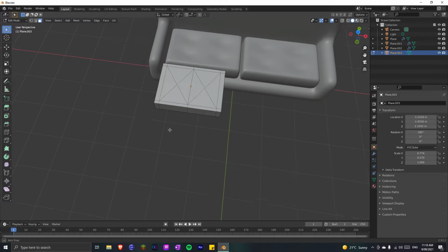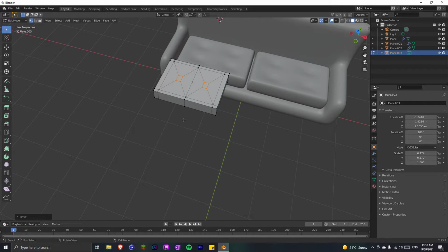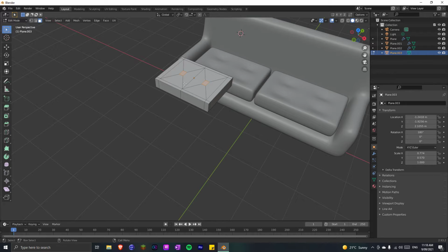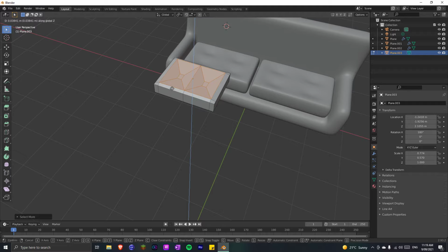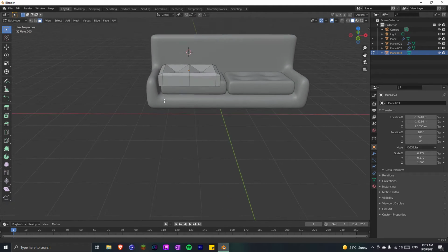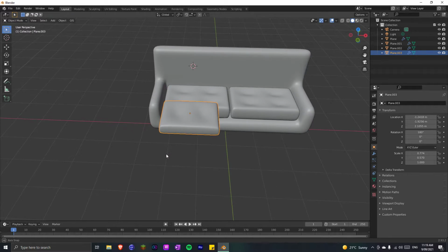And now you are going to need to go to 1, shift click both these faces to select them, Control B to bevel, and press V and it will add a face about that big, and then go to face select and you'll already have them selected, and you will just G and Z and move them down a little bit just like that. And you also do Control and then numpad plus to change the selection, and then we're going to move this up a little bit just to make the pillow a bit more puffy. And now back in object mode, we can do Control 2 for a subsurface modifier and we shade smooth.